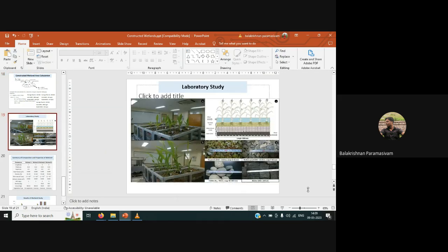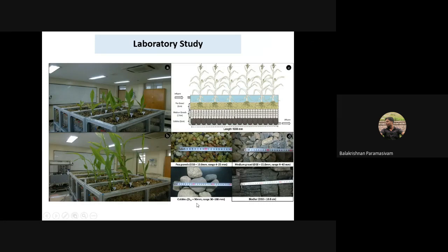So you can try this kind of laboratory experiment. This is a very simple operation, simple design. There is not much design complication, and you can use different filtration media, varying the depth of each filter media, varying the weight of each filtration media, and using biochar. And this biochar you can manufacture from any organic waste.